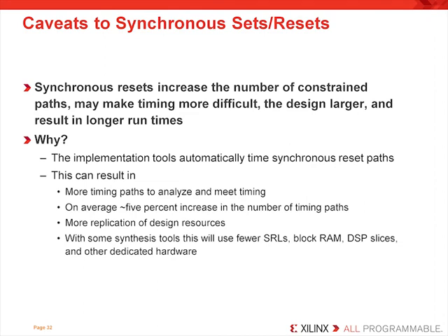But as I said, this is still better than the design not operating at all, which frequently happens with the use of asynchronous resets and when they're used inappropriately. And also having to spend many hours of debugging your design if you use an asynchronous reset. So even though there are some caveats, we still strongly recommend that you build with synchronous resets. There are simply too many benefits.